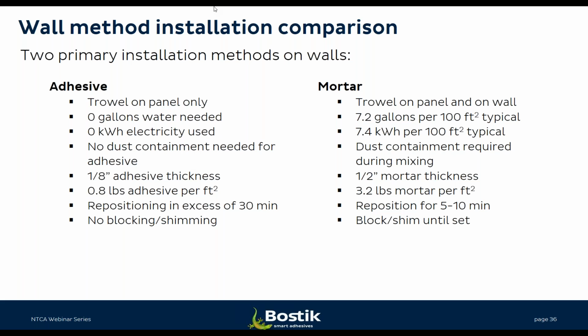So the material doesn't require any water. You can stage the material exactly where you need on the job site, despite having to chase down electricity or water sourcing. There's no additional dust containment needed for the premixed adhesive type method or the elastomeric adhesive method as well. So both of those contribute to another way to optimize installation.